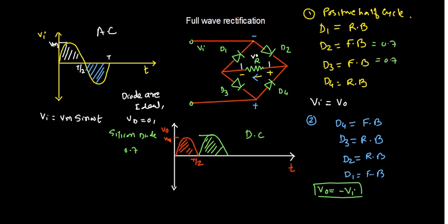So for our total VDC conversion, when you write the equation for VDC, it equals two times, we are getting two half cycles, so two half cycles in the positive part, 0.318 into Vm. But this is for ideal.